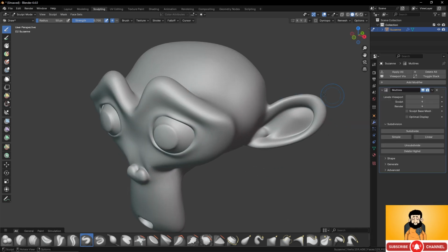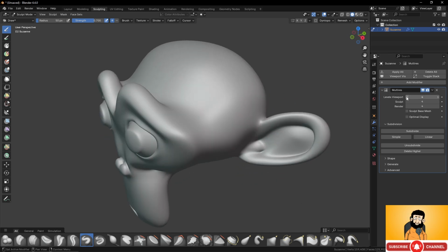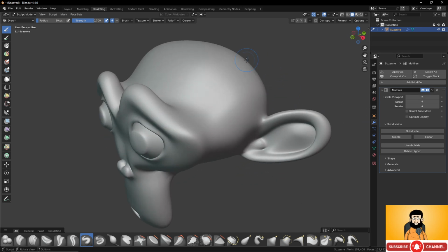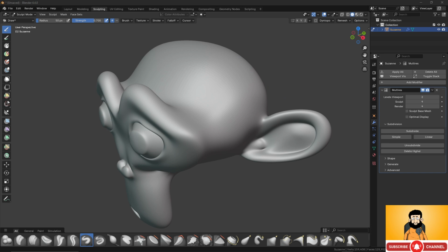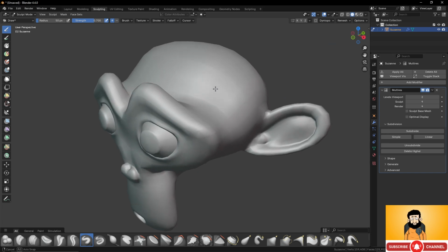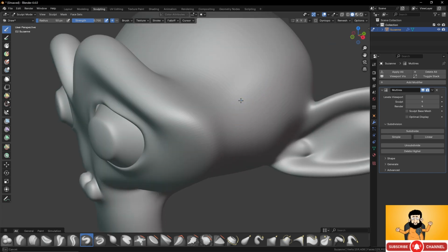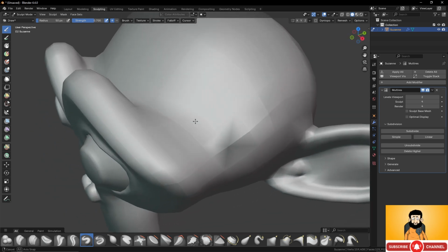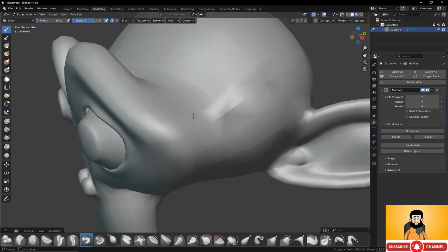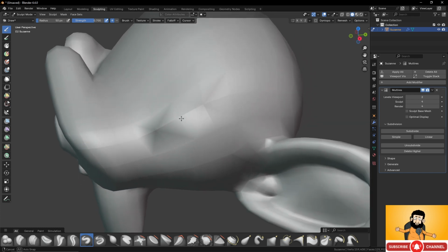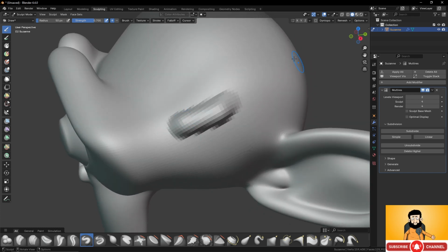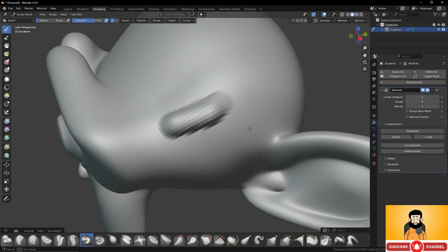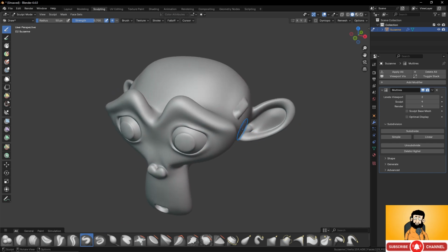If you just increase that, it will be easier. And you have a possibility for navigation to keep this, because sometimes you sculpt some details here, and when you turn around you will not see the details anymore, because it gives you a fast navigation when you turn around the object. So to disable this, you can go into the options and remove the fast navigate. Like this, you always see the details that you did sculpt, okay?